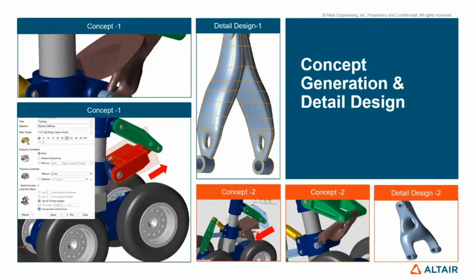For example, titanium stock versus titanium powder, which is required for, say, LPBF, a laser based printing process, is 30 times costlier, right? That can be one of the reasons. Another reason is the application where it is used. For example, aircraft are extremely sensitive to weight.